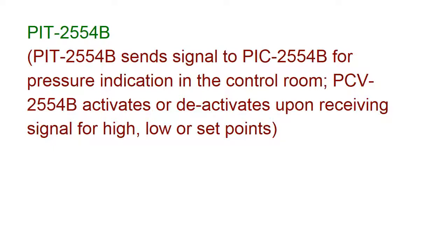PID2554B. PID2554B sends signal to PIC2554B for pressure indication in the control room. PCV2554B activates upon receiving signal for high, low or set points.